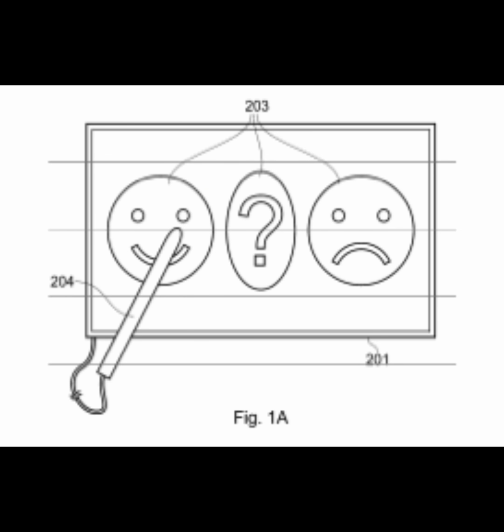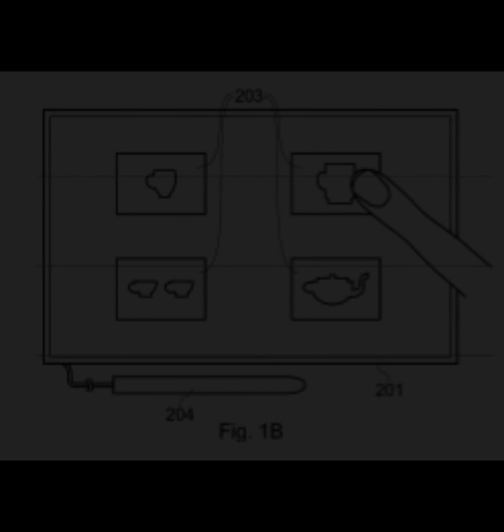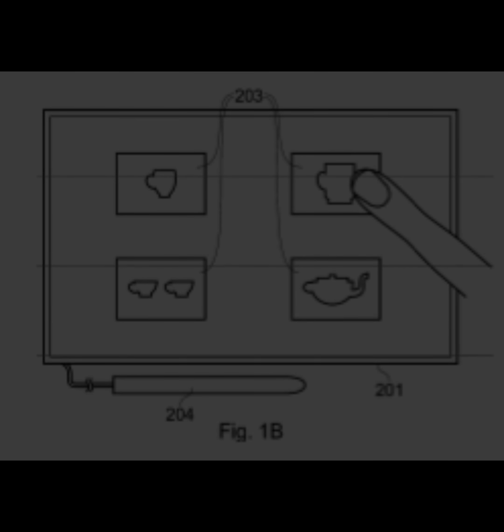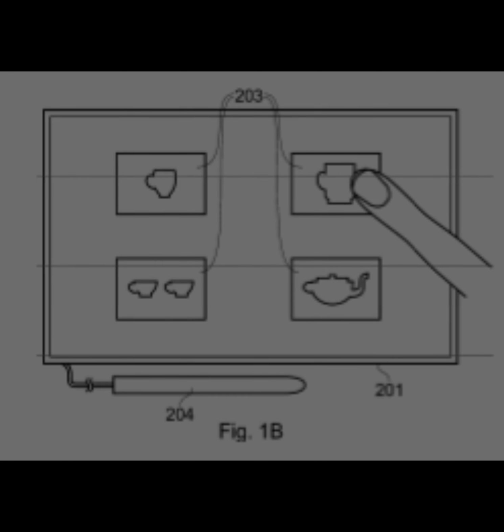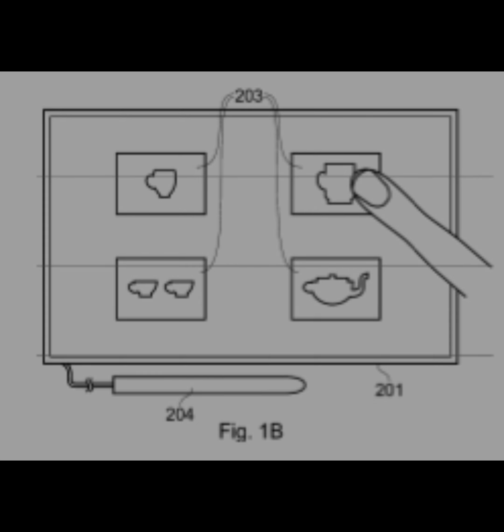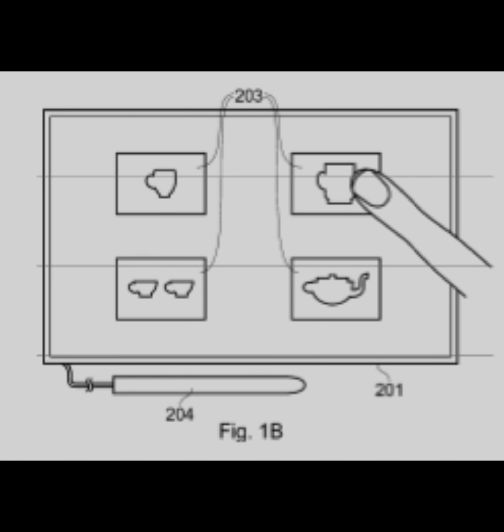Our invention is a joystick which is based on the principle of operation of the potentiometer described above. As shown in Figure 2, the joystick 111 comprises a hollow, hemispherical, and electrically insulating support 112, which is closed by a cover 113. An actuator 114 is pivotally mounted at the center of the cover by means of a ball joint. The ball joint comprises a ball 115 arranged on the actuator and a socket arranged in the cover for retaining the ball.